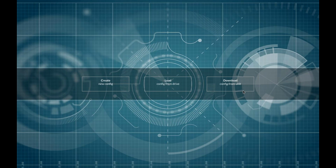The third one is to download an existing configuration that is already living in my mixing system. This might be useful if, for example, you lost the original design, or maybe you're doing a service call into a venue where they have custom control in use and they need to change something, they need to diagnose some problems. So you can simply download the configuration on your custom control editor, provided, of course, you have the admin password if a password is set for that system.